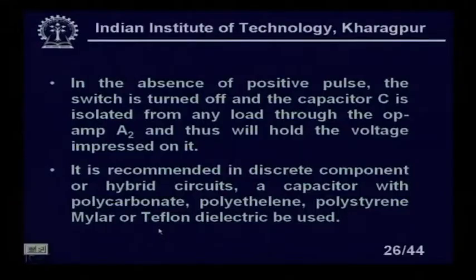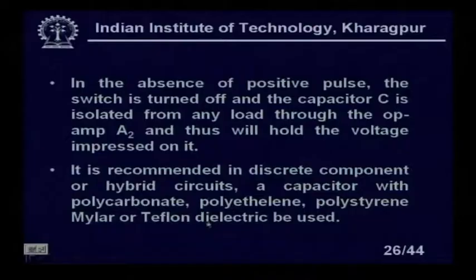It is recommended in discrete component or hybrid circuits to use a capacitor with polycarbonate, polyethylene, polystyrene, mylar or Teflon dielectrics, because all these names actually came from the typical dielectrics of the capacitors. This is the dielectric which is placed inside the plates of a parallel plate capacitor. We are not necessarily talking of parallel plate; it can be foil type also, as happens in the case of electrolytic capacitors.